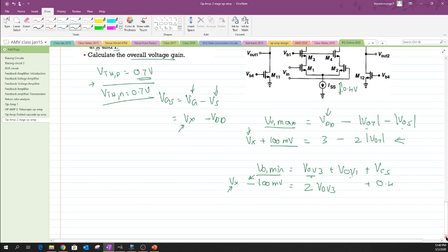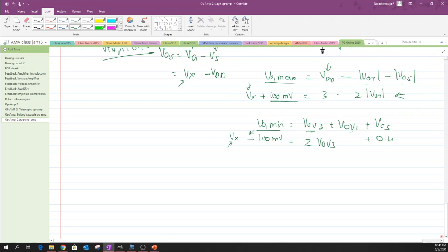So now let us talk about the drawbacks one could have when we try to have more stages. Specifically, when we look for the drawbacks of a two-stage op-amp, since there are two stages between the input and the output, each individual stage in turn adds a particular pole in a system.